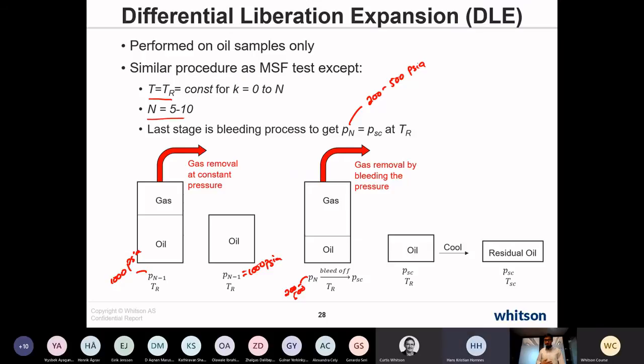That's where you'll start seeing big differences in the final atmospheric pressure volume of oil, which will differ substantially from the lab experiment versus doing a single flash from, let's say, 400 psi to 14.6 psi. The difference can be 5% difference, it can be 20, 30, 40, 50% difference if it's a high enough temperature and a light enough oil.